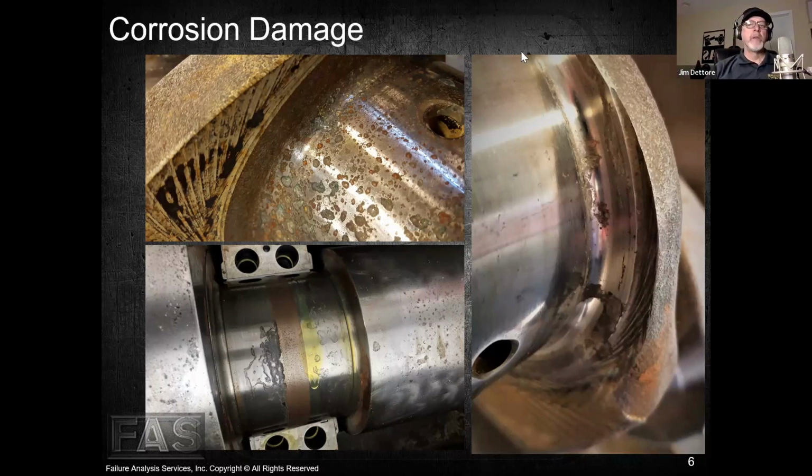And we've seen it where a hailstorm will come through and go through that aluminum tape, and now it's open, and now it can rain, and that rainwater gets in the exhaust manifold, looks for an open exhaust valve, and fills up the top of the piston area, and then runs down the side of the cylinder wall and drips right here on the crankshaft.